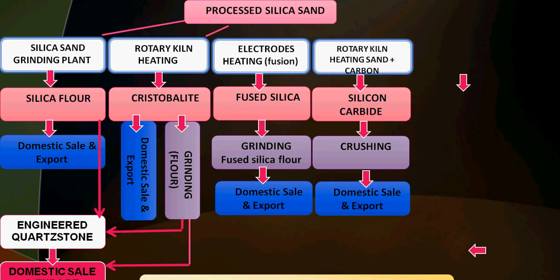It is used as an abrasive, polishing agent, for cutting tools. It is used as refractory material. More recently, a more advanced use of silicon carbide is the production of thin wires. And these thin wires are used to cut the silicon wafers to produce solar cells. Before the invention of these wires, the silicon wafers were produced by the diamond saw. So there was a loss of waste. When we use thin silicon carbide wires, there is no waste, or very little waste. So silicon carbide is another investment.